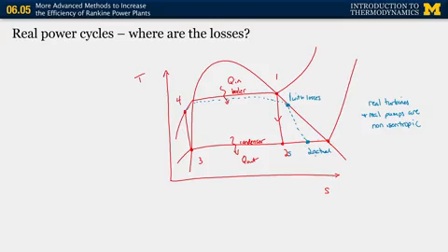The exit state of the turbine still has to hit that exit pressure, the entrance pressure to the condenser or the exit pressure of the turbine. And then again, in a heat exchanger, we'll indicate our losses as being pressure losses. So it would look something like this. Okay. And nominally, you're not going to lose pressure below the ambient, right?